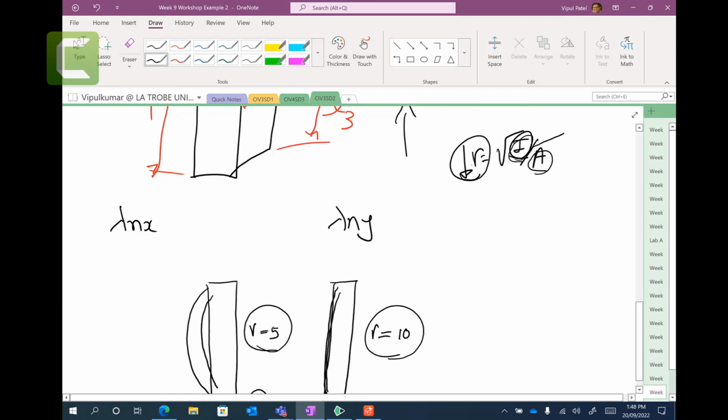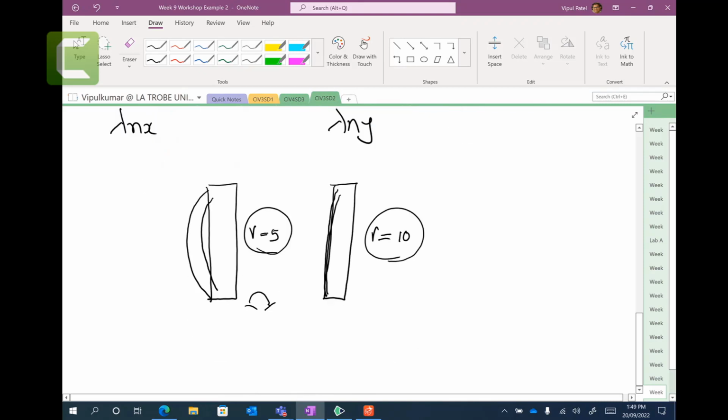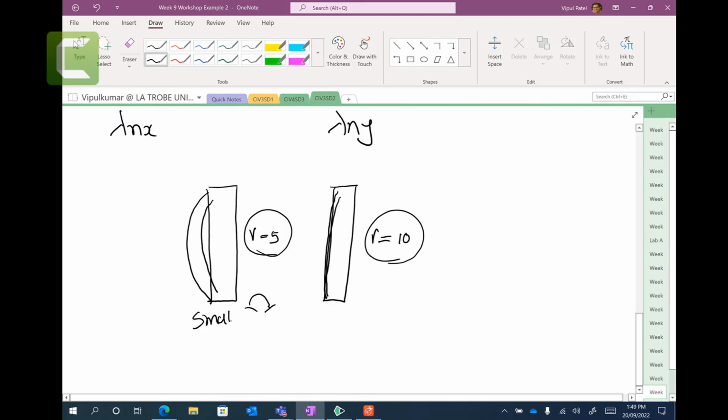If you have less resistance against the bending, your geometry's I is less. If you have a smaller I, you get a smaller r, meaning small resistance against bending. So the smaller value gives you a higher chance of getting global buckling.